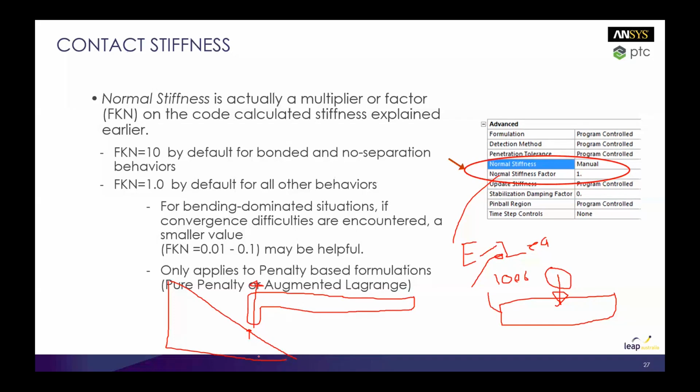Then in the next equilibrium iteration, there's a force present at the bottom here because of the contact. That's enough to deflect the arm upwards. In the next equilibrium iteration, that force disappears. The arm has some internal energy, it's essentially like a spring that's been held back.